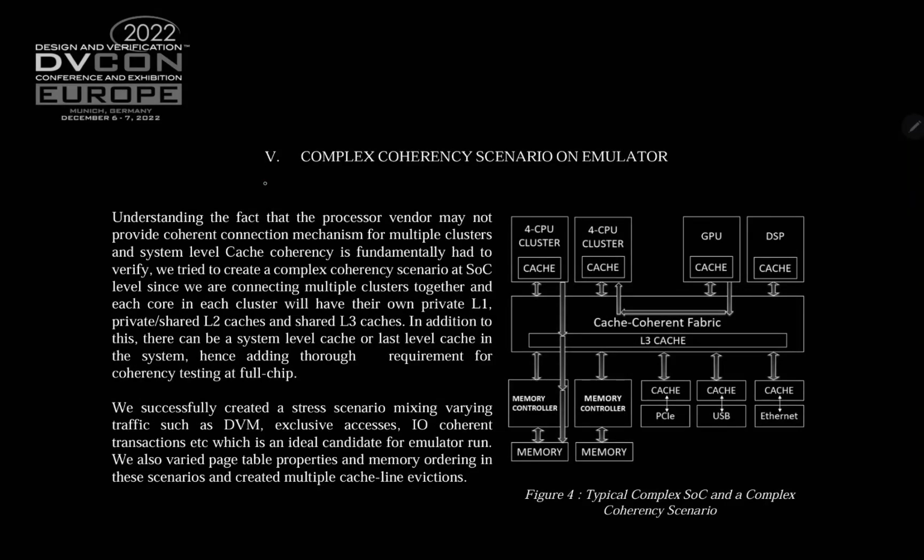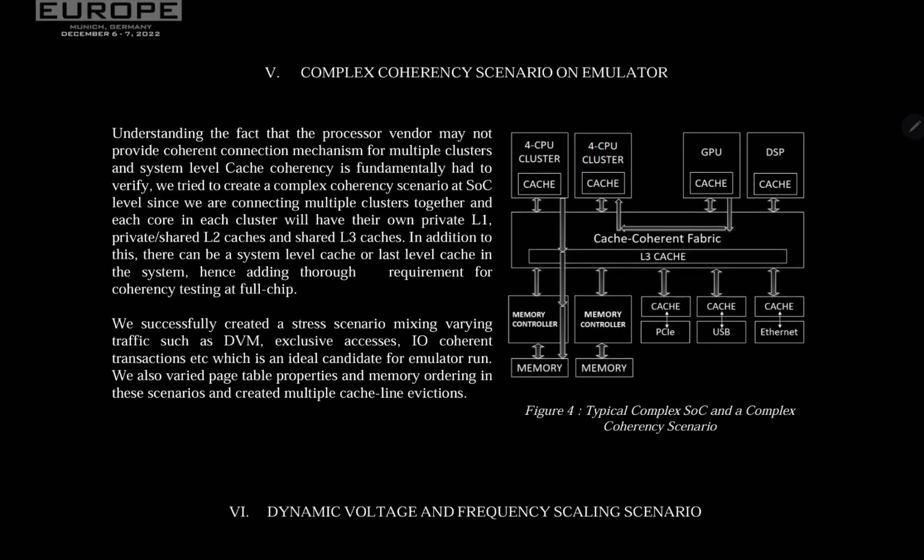Section 5, the coherency scenario on emulator. Figure 4 is a typical complex SoC and a complex coherency scenario. Understanding the fact that a processor vendor may not provide a coherent connection mechanism for multiple clusters, system-level cache coherency fundamentally has to be verified.